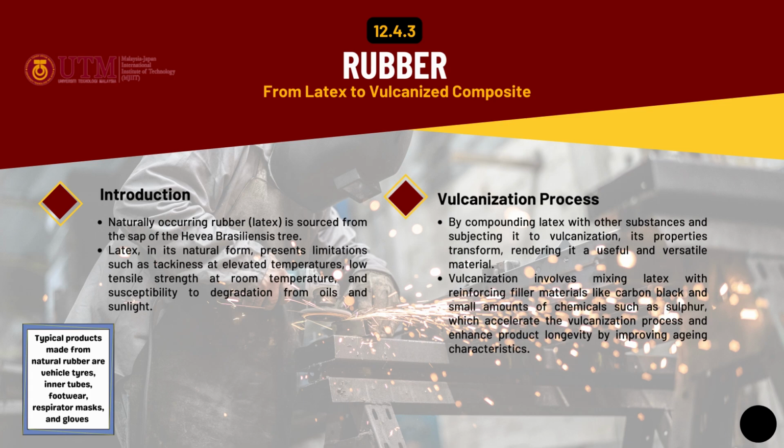Latex, in its natural form, presents limitations such as tackiness at elevated temperature, low tensile strength at room temperature, and susceptibility to degradation from oils and sunlight. For vulcanization process, by compounding latex with other substances and subjecting it to vulcanization, its properties transform, rendering it a useful and versatile material.